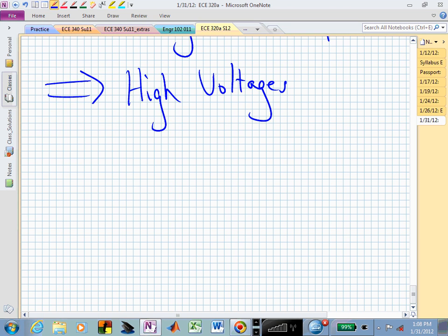Maybe I'm getting ahead of myself. Let me just say that we want high voltages. And what are these three phase? Phase means it's alternating, doesn't it? It's AC. And it's fairly easy to convert AC from a low voltage to a high voltage. A lot of these now are done more electronically than the old-fashioned way, but a lot of these ways of converting from AC down to DC to power something typically used to have a transformer in them. And that transformer allows you to convert high to low or low to high without any moving parts. If it was DC, then we would have to do something a little bit more extravagant. If we had high DC lines feeding our DC loads, we might want to drop them down. Well, with AC,